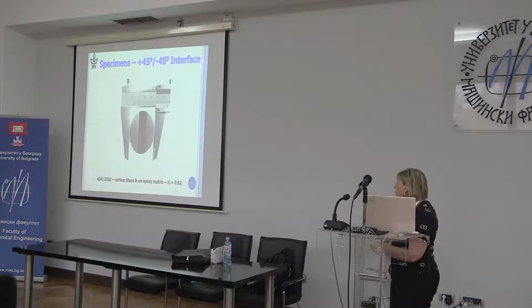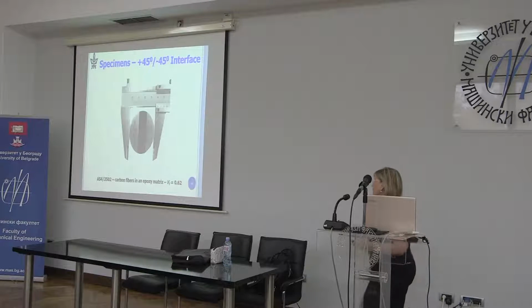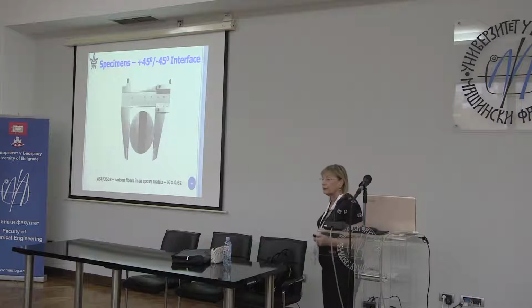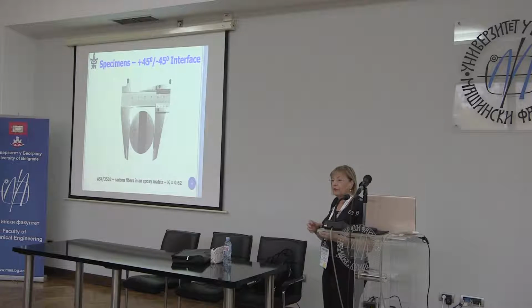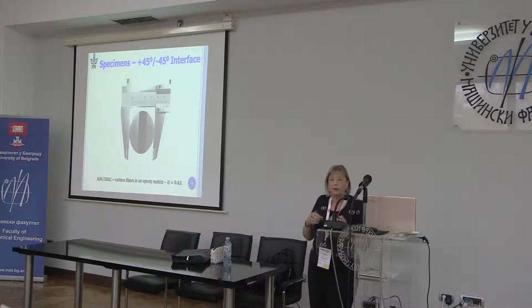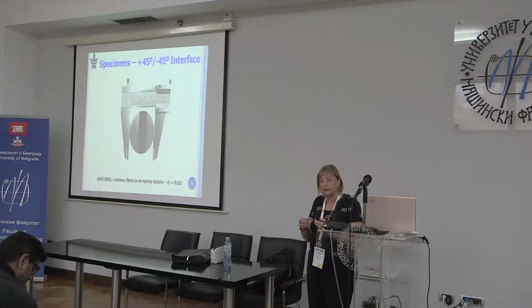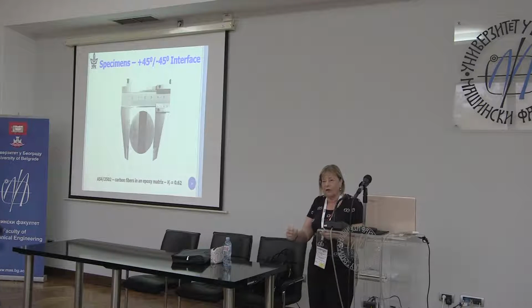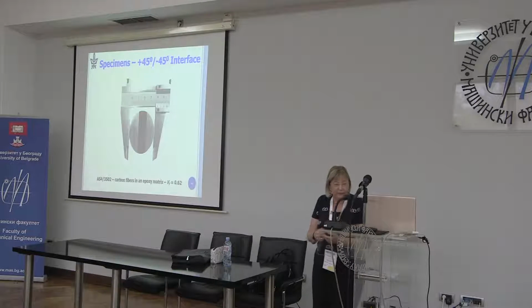And we have a volume fraction, I didn't really go into that, a volume fraction of 62%. So you measure the volume fraction of how many fibers you have in the matrix. 60% is common. People don't use them with 40% or 20%. They go up to 60% because the carbon is what holds the load. The matrix is there just to hold the fibers together.